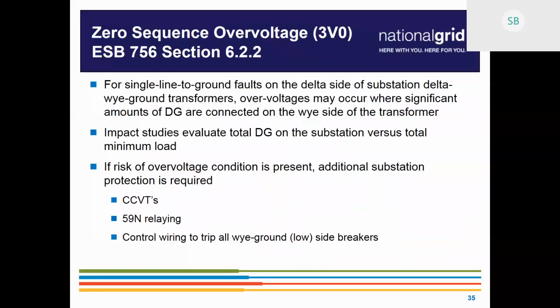For moving the relay requirement to your side of the meter, can that be in effect for projects that already have their ISA but haven't been built yet? Is that something where we could change the design, or is this only for new projects that get applied for after this date? It is something you'd be able to do if you haven't yet completed the site and have your ISA. We've been careful about how we put it out there because it's not mandated. So if it's more difficult for you at a particular site to move it, you don't have to. If you want to, you can.